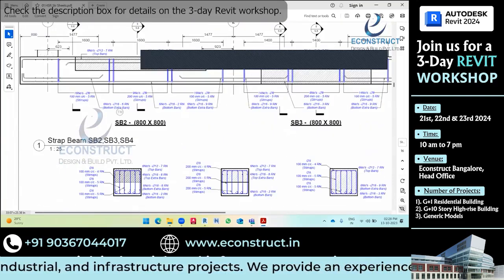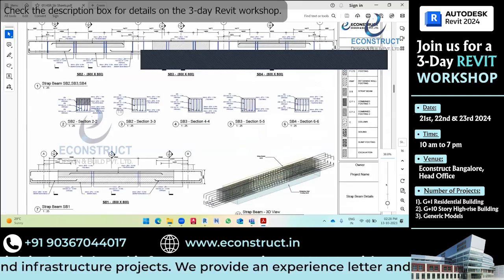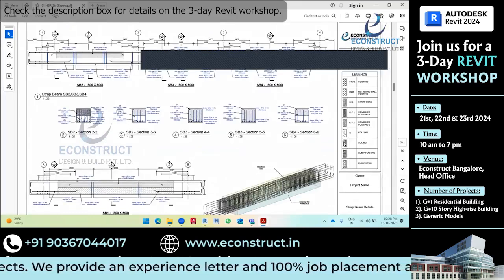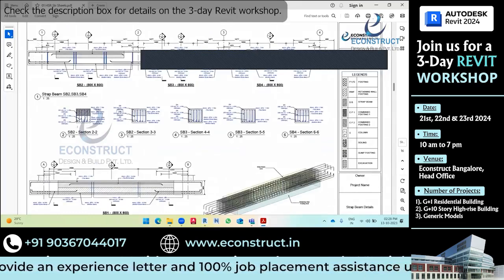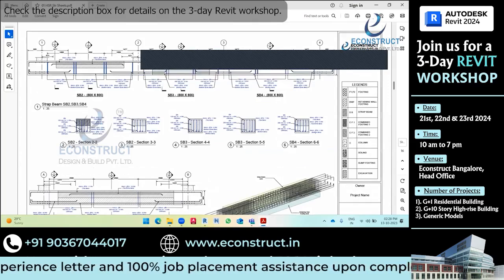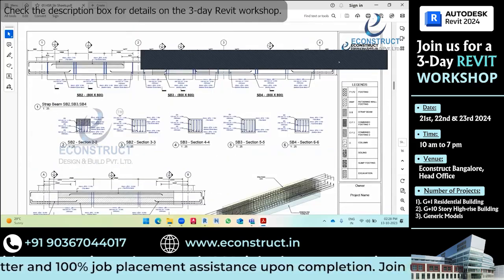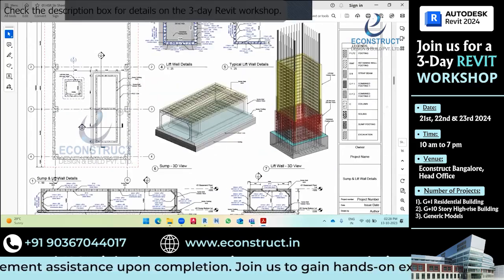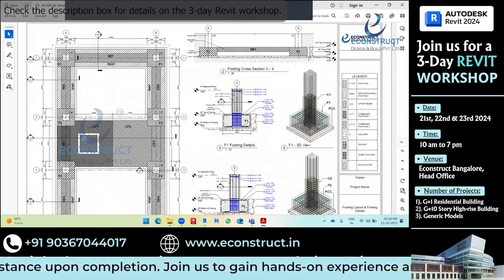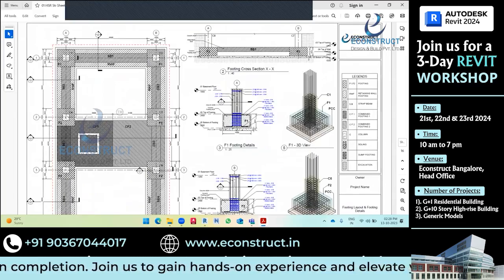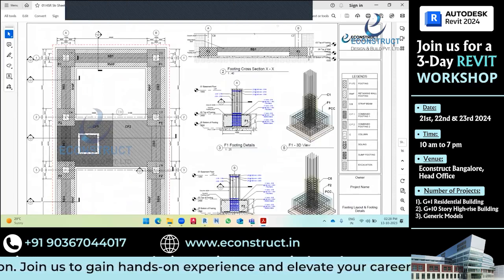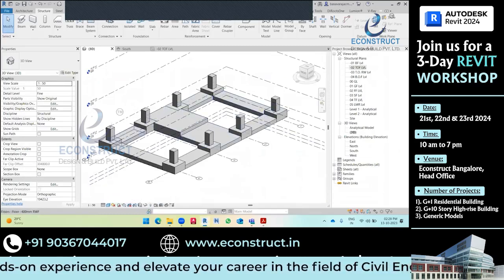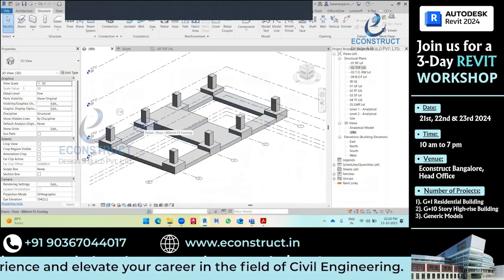See, this is the strap beam sheet. Here the dimension of that beam is written. 800 mm height. And in the plan, we have given the width also as 800 mm. Width is 800 mm and depth is also 800 mm. So we need to create one beam now. So how to do that? And it is coming from the top of the footing level.